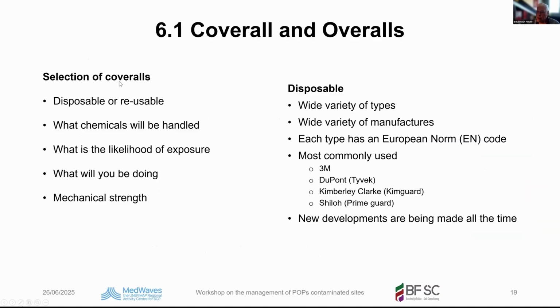Okay, selection of coveralls, disposable or reusable. What chemicals will be handled? What is the likelihood of exposure? And what will you be doing, and what mechanical strength is needed? Disposable, a wide variety of types, a wide variety of manufacturers. Each type has a European norm, most commonly used, and here are the companies: 3M, DuPont, Kimberly-Clark, and Ansell. But new developments are being made all the time.